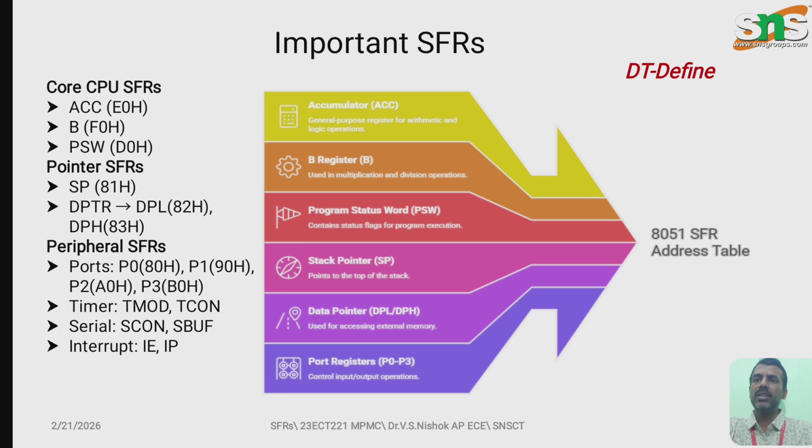The pointer SFRs are classified into stack pointer and data pointer, and the peripheral SFRs are classified into ports P0 to P3, timer circuit, serial circuit and interrupts.